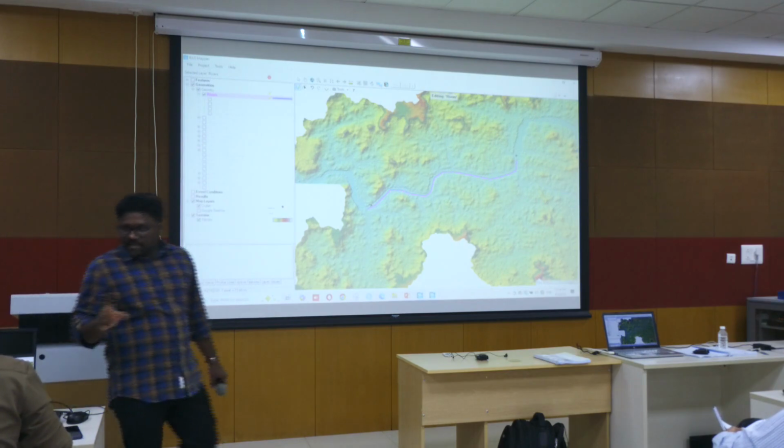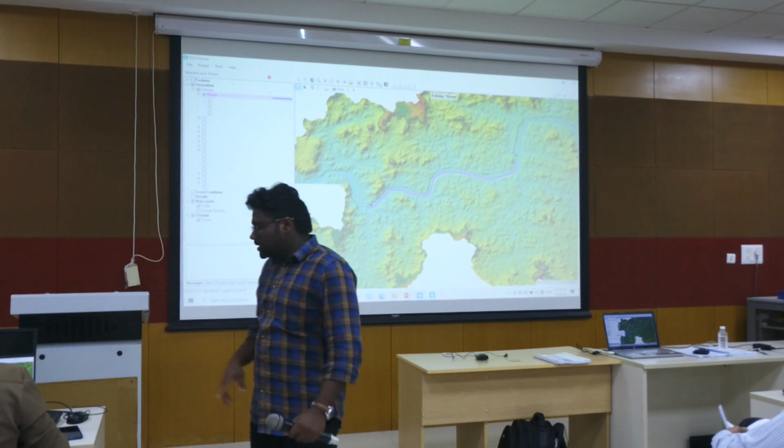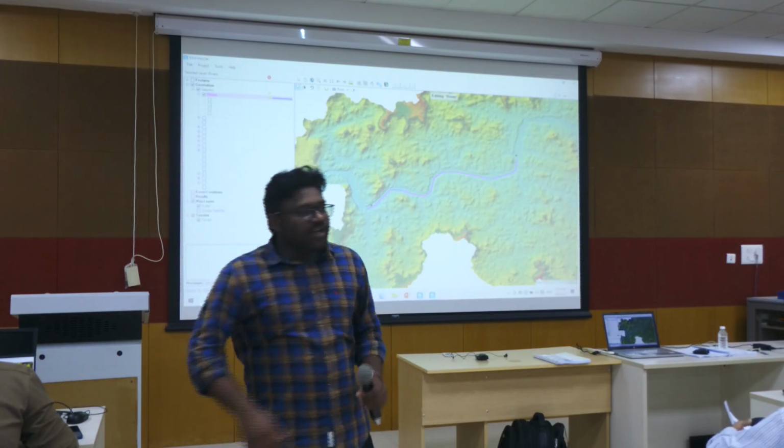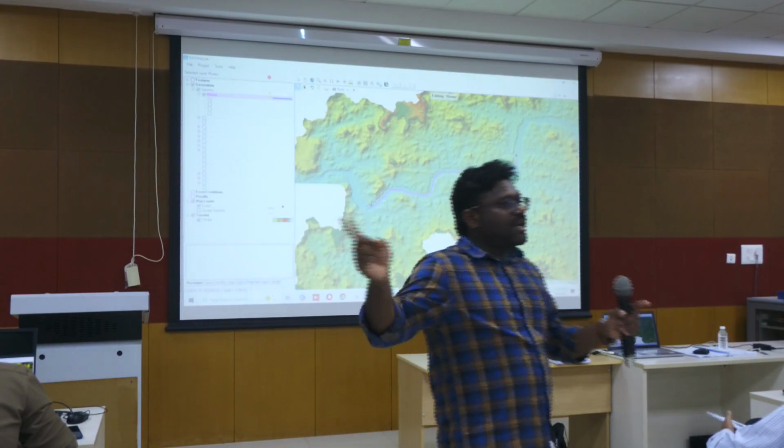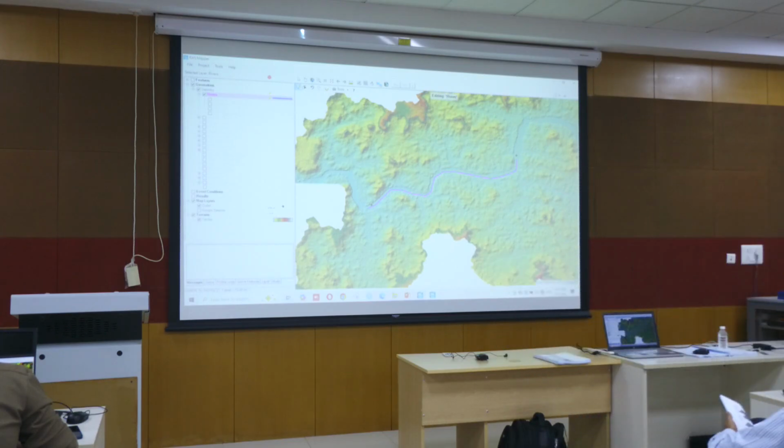That's why you cancel it again. It should be a continuous reach. If it is creating twice, meaning reach 1, reach 2, you just click Control Z. It will come back. It should be only one reach. Reach 2 means again it is a second river.